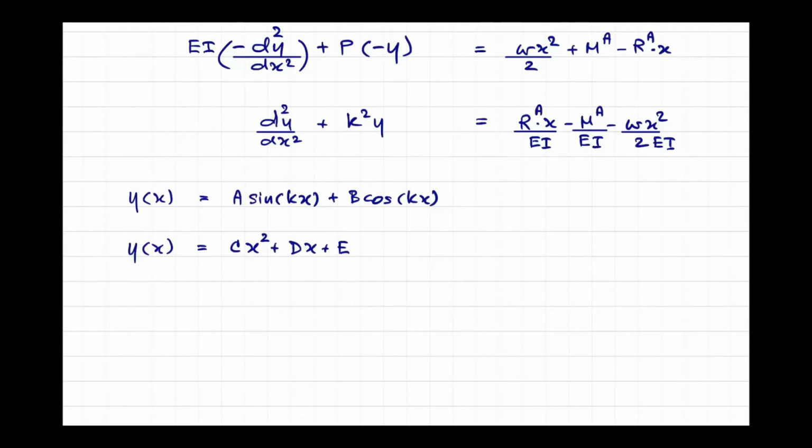Right? In the real structure testing, we sometimes want to learn about the dynamic characteristic, like the natural frequency. You learn in dynamics. We want to figure out the damping ratio. We want to figure out the mode shapes of the structure. So that could be done in the field, and that uses different kinds of sensors.